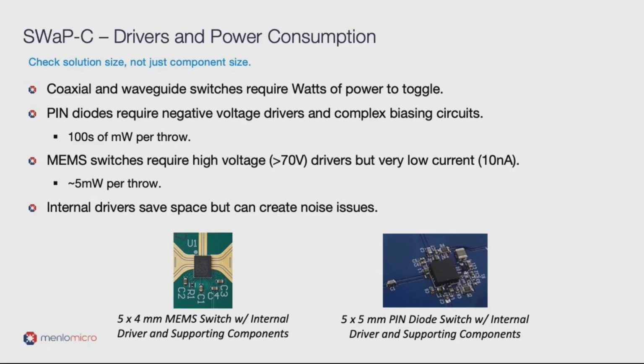One thing to note when discussing power is the potential design challenges brought by drivers, besides just their size and power consumption. Pin diodes require negative voltage drivers to operate, which can be difficult to design. They also require supporting components to properly bias the switches and tune performance for a given frequency range.